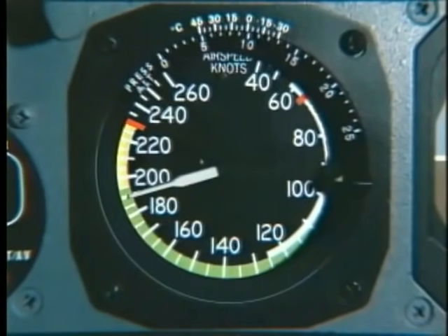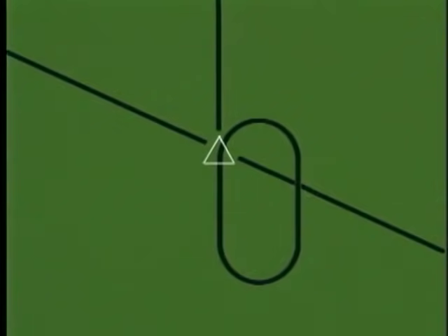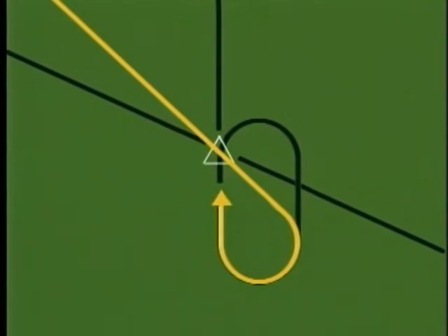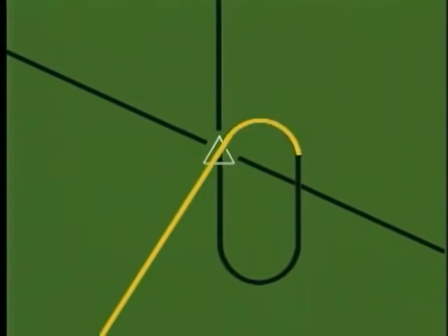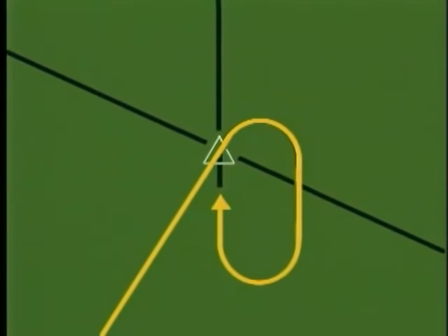If the indicated airspeed of your airplane exceeds the maximum holding speed, you should reduce it at least 3 minutes before your ETA at the holding fix. To minimize the amount of maneuvering you have to do, the FAA recommends that you enter a holding pattern by one of three methods. Use of these procedures makes the entry simpler and reduces the possibility of penetrating unprotected airspace.